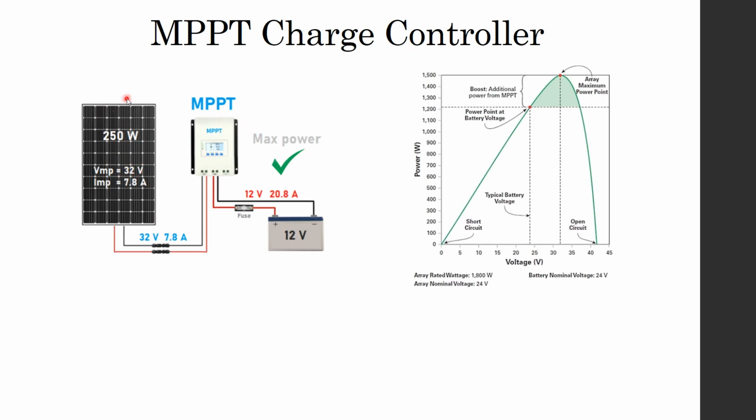So here we have a panel connected to the maximum power point tracking charge controller connected to the battery, okay? The battery itself has 12 volt as a battery voltage. This is a constant value. The output here is a constant. So if we make the panel voltage at 12 volt, for example, then we will have a certain value less than the maximum power produced, okay?